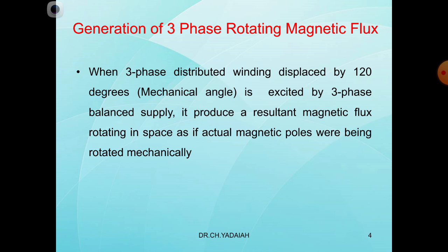the stator establishes its own magnetic field. Due to the three-phase supply, R phase, Y phase, B phase, with frequency 50 Hz and 120 degrees apart from phase to phase, the current flowing through the winding changes its value at different instants. So it induces a magnetic flux of 1.5 times that of each phase produced by its own winding.